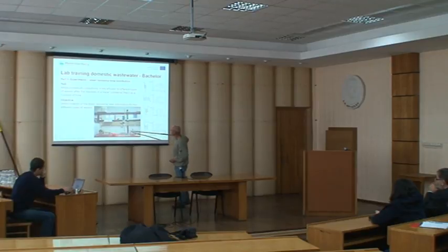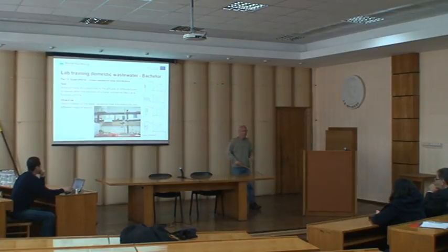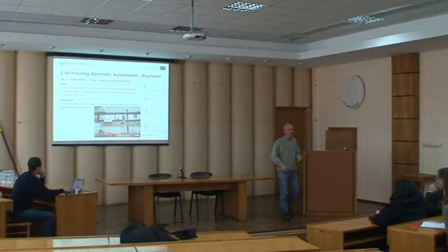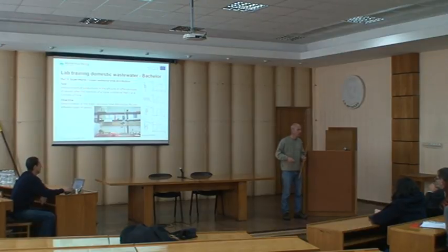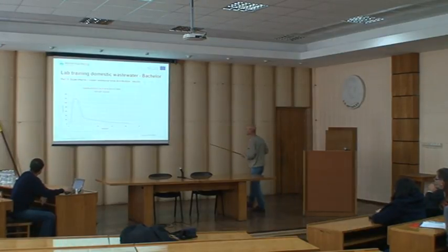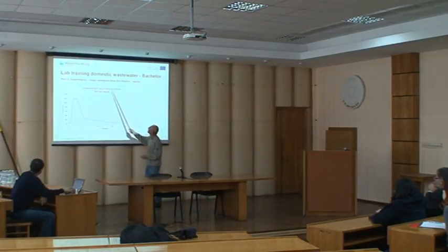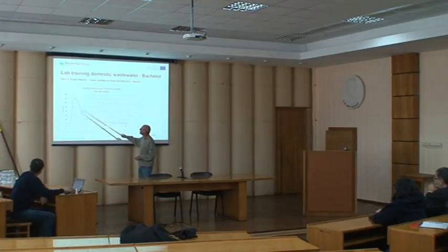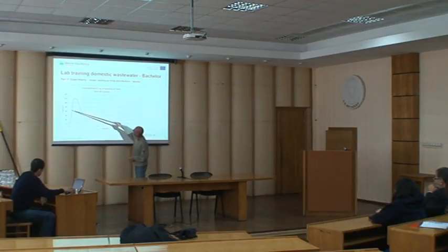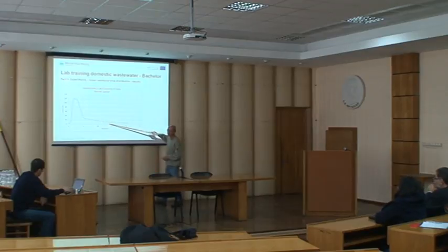We use deionized water in the system and the salt solution injected by the syringe at once, and then you're measuring the conductivity in the effluent over the time. Every minute you do a measurement. And here you see a real measurement of students for a stirred reactor. You see the conductivity, you see the time, and this is the behavior of the system over the time. So they're doing it for different types of reactors, and they have to compare it.